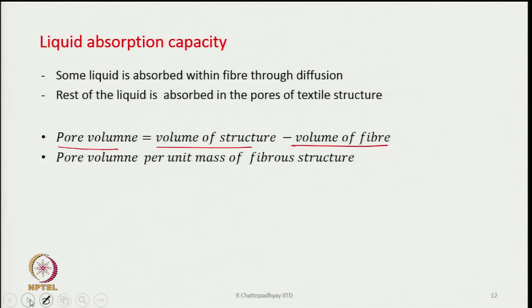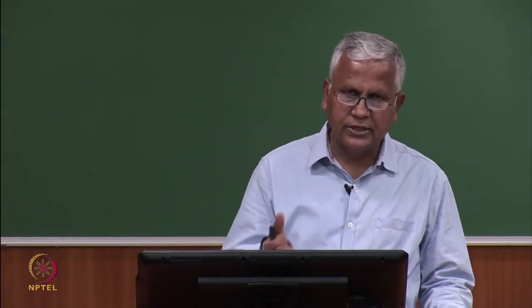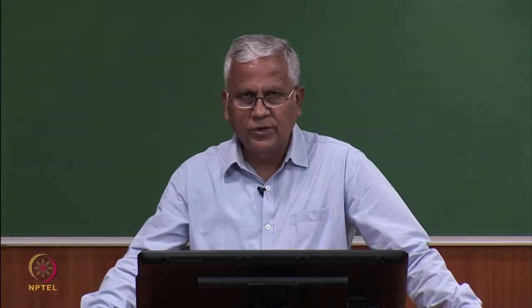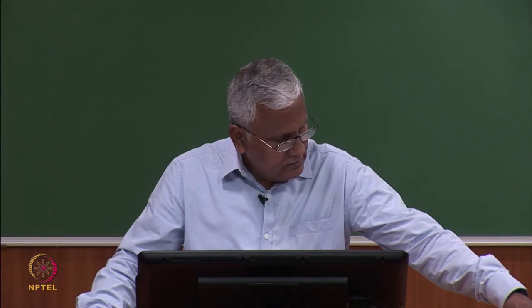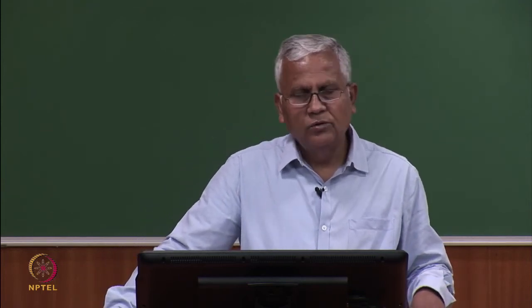Generally, we use non-woven type of structure for such kind of applications, because non-wovens, first of all, are a very nice process where fibers can be transformed into a medium which can absorb very fast. We need not go through a long process of converting fiber to yarn, then making the fabric, going through so many stages. All those stages can be avoided. Directly we can make an assembly of fibers using a non-woven line, and there are many techniques of non-woven, but some of the technologies are suitable for cotton or rayon, we can use them.